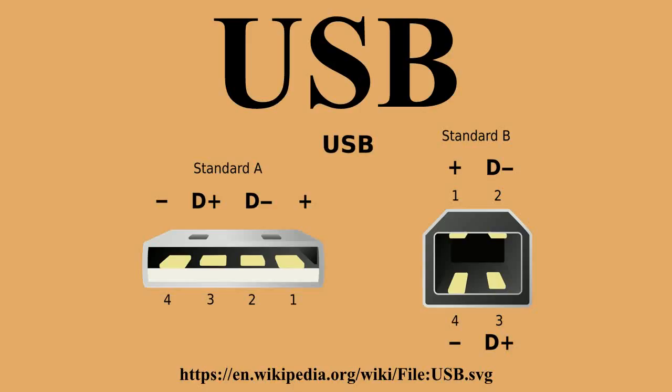On-The-Go allows USB between peers without discarding the directed topology by choosing the host at connection time. It also allows one receptacle to perform double duty in space-constrained applications. There are cables with A plugs on both ends, which may be valid if the cable includes, for example, a USB host-to-host transfer device with 2 ports, but they could also be non-standard and erroneous and should be used carefully.